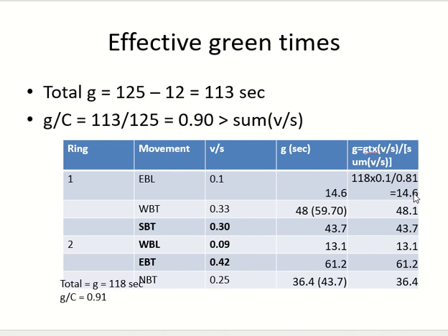So this 7 seconds, obviously now you don't have any choice. This 7 seconds will be added here. You have to make them equal. This is the thing which they did. After they did this, this gives me effective green time. I know effective green time now. I don't know actual green time.